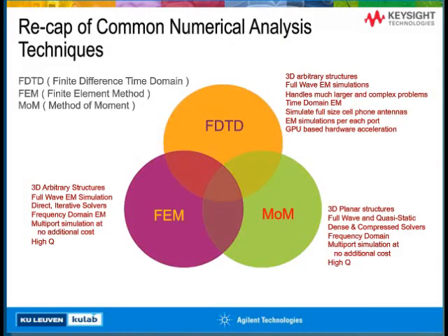So let's take a look at the common numerical analysis techniques. In the marketplace, there are 3 prevalent EM simulation technologies. They are all great technologies and very accurate, but unfortunately, none of them is perfect. These technologies are MOM, the 3D planar EM simulation technology called method of moments, FEM, finite element method, as well as FDTD, finite difference time domain.